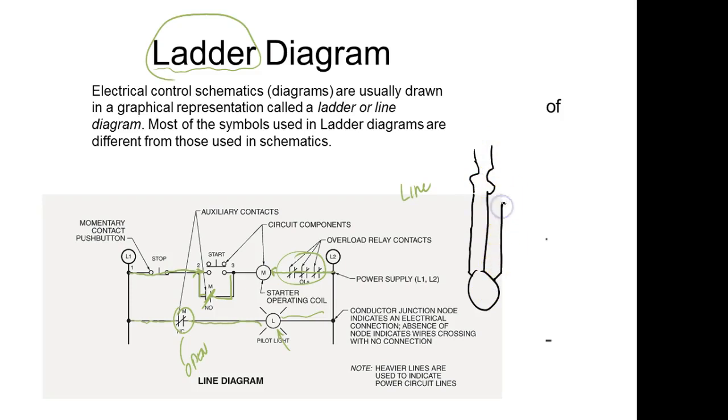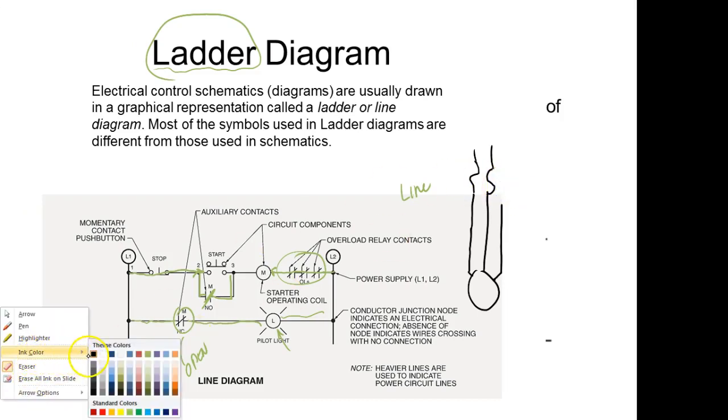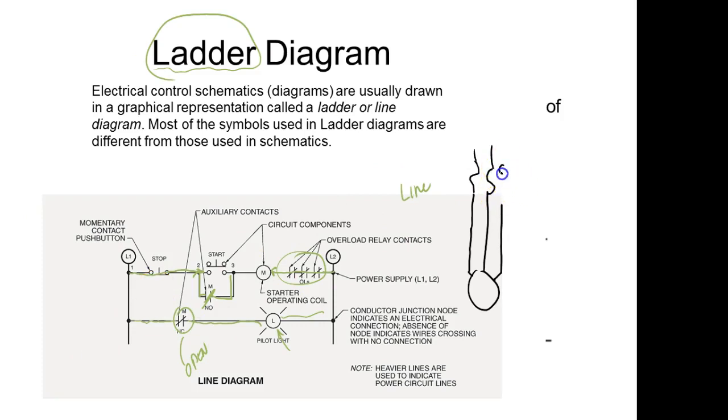Now the problem is these fuses have to allow the motor to start. So if they don't allow enough current for the motor to start, then they would blow, right? So this is a big problem we have with motors. Your fuses or your overcurrent protection devices have to let the start current come through. So what happens if the motor stalls? The fuses won't blow, because they're rated between 120 and 150% of the start current, not the run current.